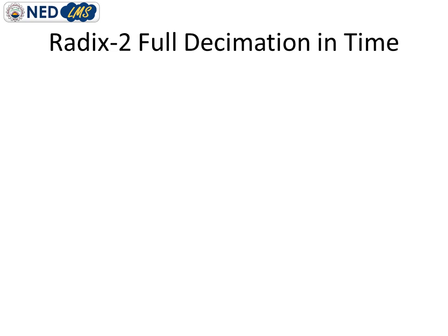So what we will do then? This is the limitation of radix 2 algorithm. However, we can solve this issue with some smart solution. We have multiple solutions for it. Suppose the first option is we can only take the consecutive samples which can be represented as the power of 2. For example, if we are provided with 5 samples, we can represent 4 samples as 2 raised to power 2. So we will take only the first 4 samples and discard the fifth sample.